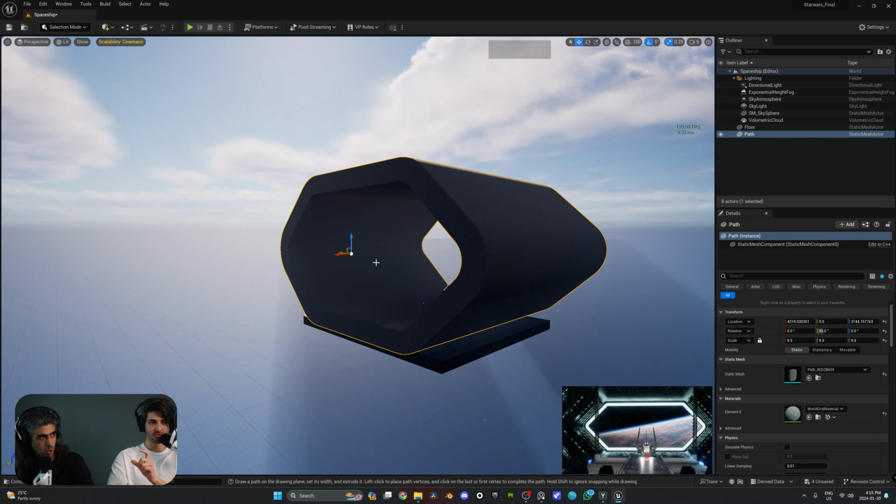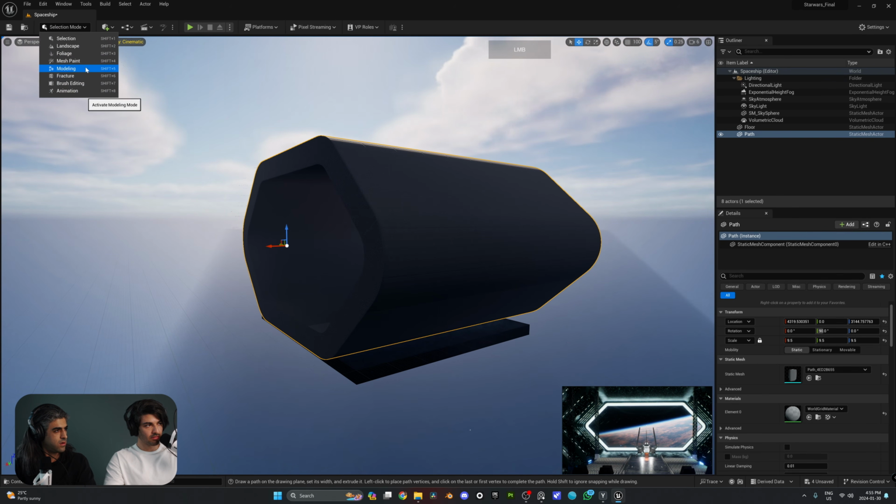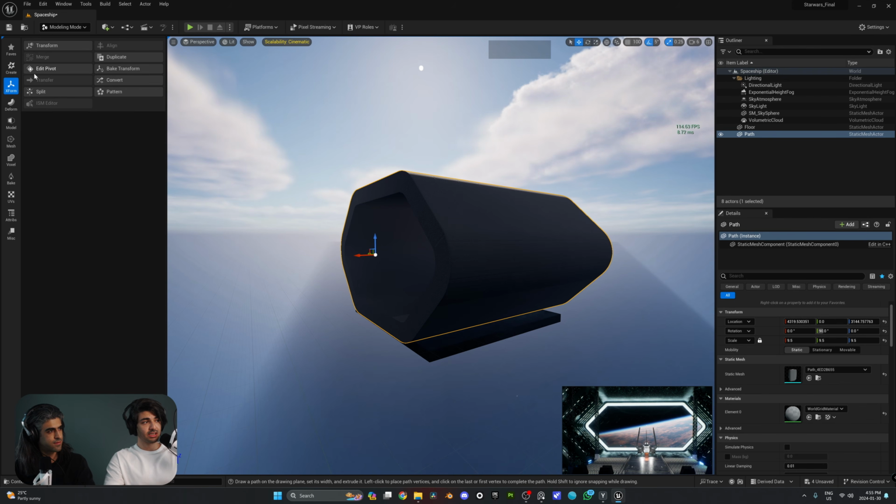Let's do it in the modeling tab. That's right. It is actually in the modeling tab. And that's why the modeling tab becomes really handy, right? And a lot of people need to start using it in Unreal. So if we go to the modeling tab right here, click modeling. And this time, whilst we have the hangar selected, we're going to go to X-form, right? And then we see something called Edit Pivot. Pivot!